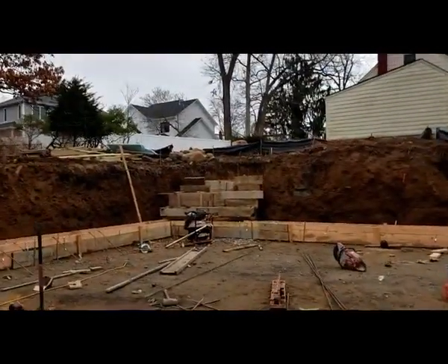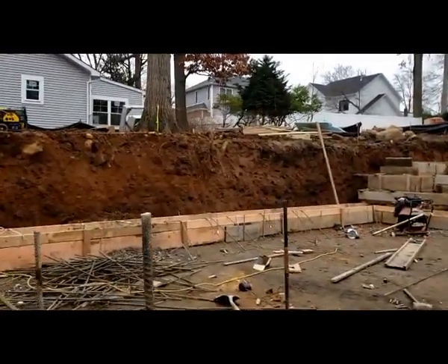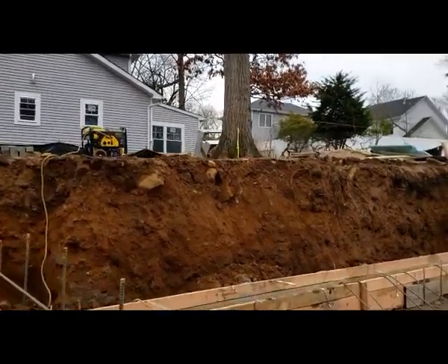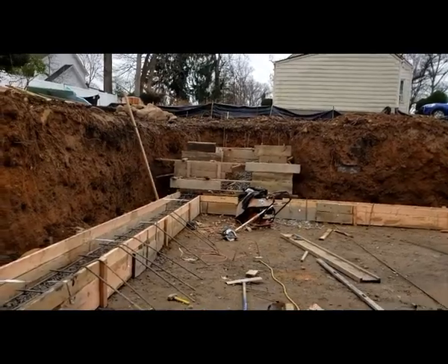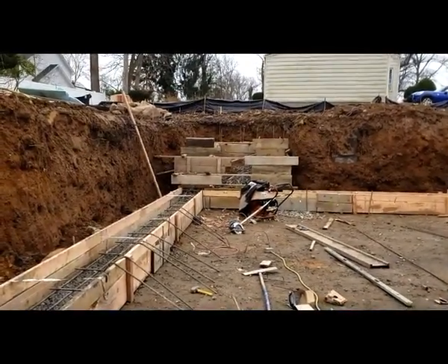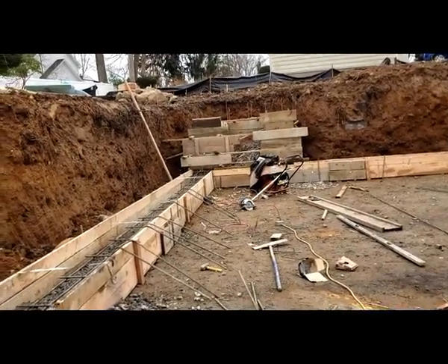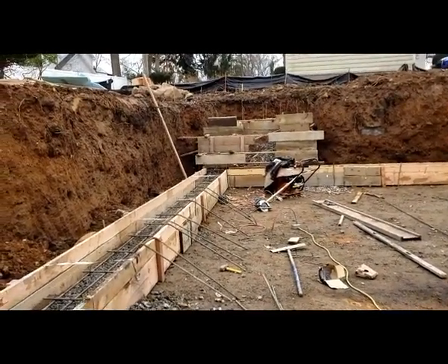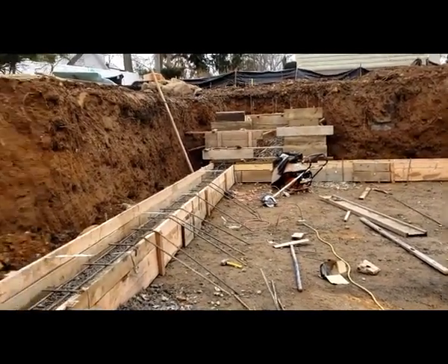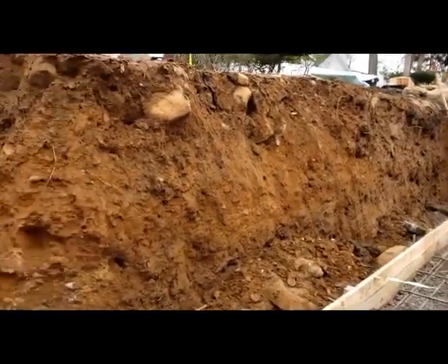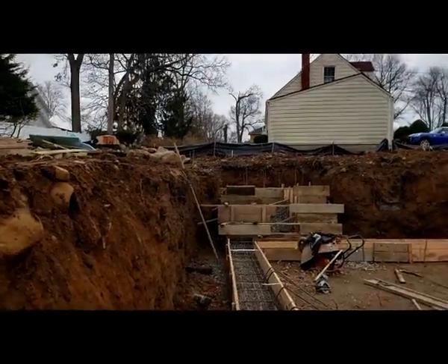Now if we go back, we'll see the footing. Now I like to do it monolithic. This is all the concrete goes together in a monolithic pour. That would help you to prevent any settlement, making one more solid unit that acts together. So this is the way I usually do it. And here you go. That's it.